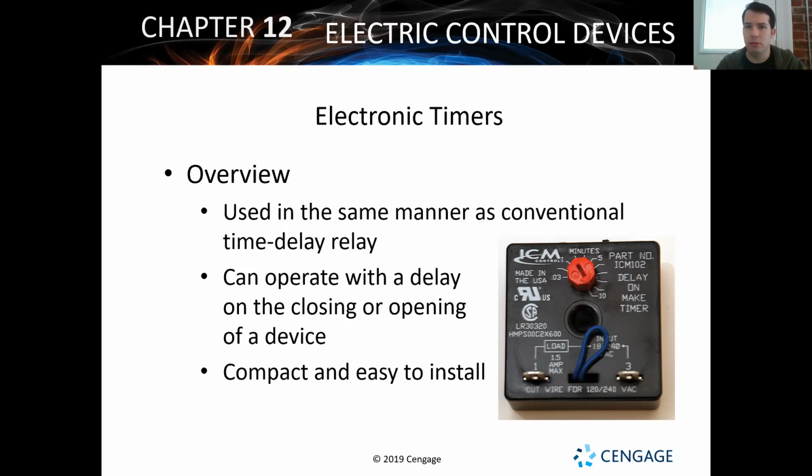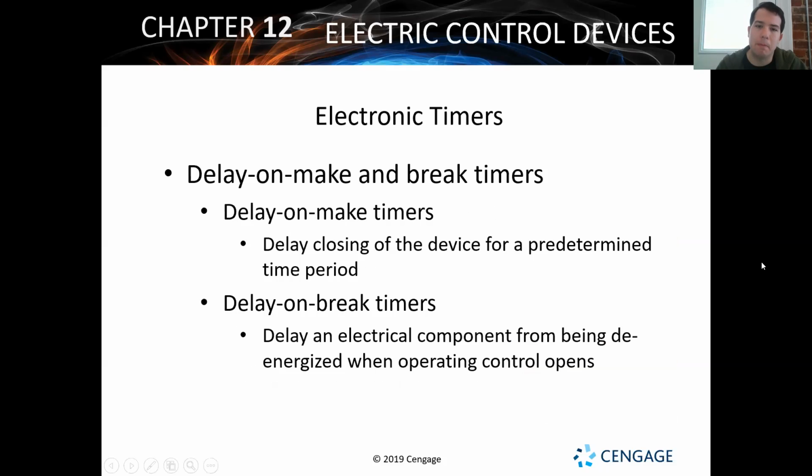The problem is, if the motors aren't working or the pressure systems are shutting it off, they're only going to wait until that pressure or the temperature, whatever kind of delay, if it's a pressure or temperature delay or switch, all it's going to wait for is once the pressure gets back down to normal, once the temperature gets back down to normal, then it's going to fire right back up again. So having it where it's not a pressure or temperature, but literally just time is all it's waiting for, that's one of the biggest advantages to these systems.